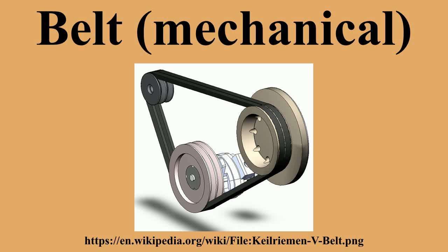Belt tension. Power transmission is a function of belt tension. However, also increasing with tension is stress on the belt and bearings. The ideal belt is that of the lowest tension that does not slip in high loads. Belt tensions should also be adjusted to belt type, size, speed, and pulley diameters. Belt tension is determined by measuring the force to deflect the belt a given distance per inch of pulley. Timing belts need only adequate tension to keep the belt in contact with the pulley.